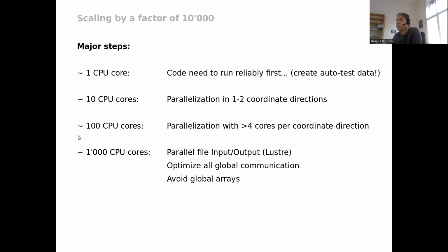If you go to 2000 cores, then you have to start thinking about your IO scheme, so how you save the files. Writing with 1,000 processors to a storage system, no matter how capable it is, starts to become a pain. If you have 1,000 processors that want to open new files at the same time on the same storage system, it definitely does not have 1,000 hard disks, it has fewer. So there will be a clash. Something will be clashing somewhere, right? You may be blocking one IO with another one. So first, that is what you have to think of.